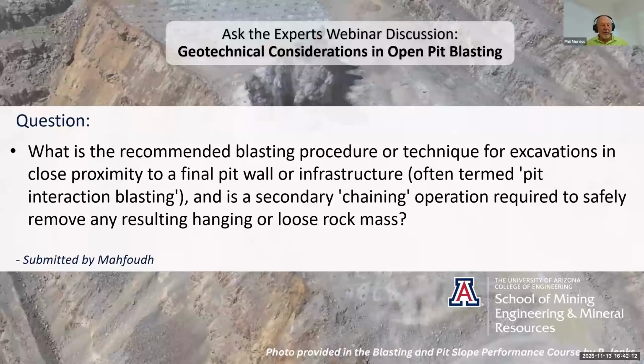Yeah, just as a comment, chaining, I'm certainly seeing less of, and part of the issue is that as we get better at achieving steep overall slope angles, or optimizing them, should we say, we haven't got berms that are sufficiently wide to allow safe operation of the dozer in the first place. As an absolute minimum, even if you've got a small dozer, you need probably 8 to 9 meters minimum width. And if you've got any toe or substantial variation in crest loss, then that becomes a dangerous operation.